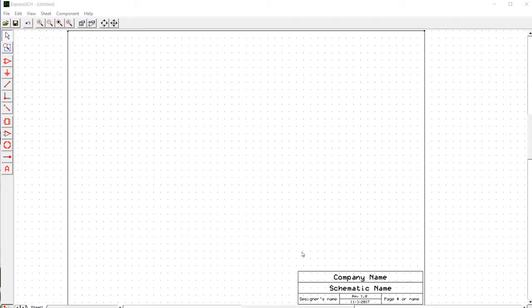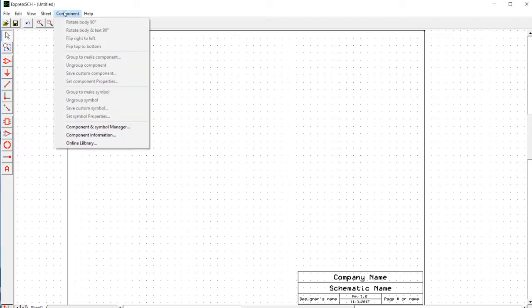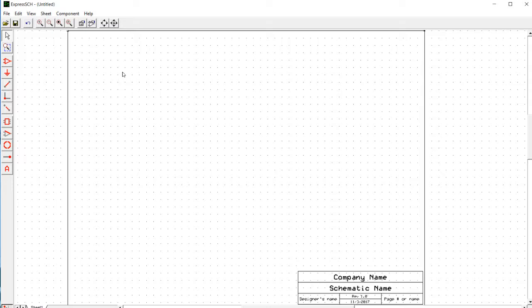In this video, we'll look at creating a custom component, which is a step that you'll need to take in the schematic software for all 4 of the sensors that you're using in this project. When you're using a standard library component, or the power and ground symbols, you just come to the component manager, which has a whole library of options. If you need to represent, for example, your temperature and humidity sensor, you'll need to create that custom because that's not a component that exists in the component manager.